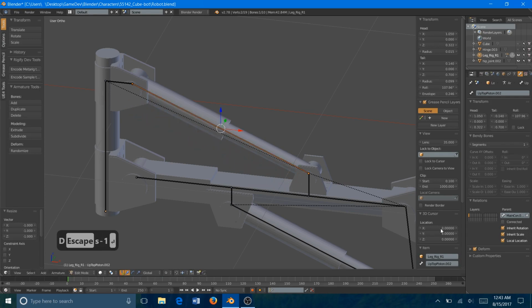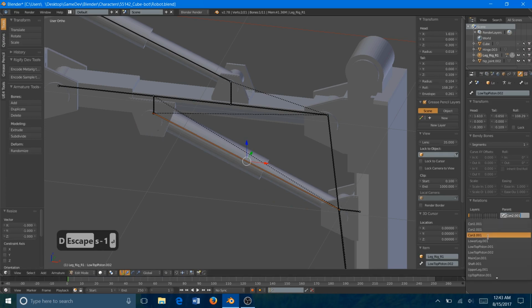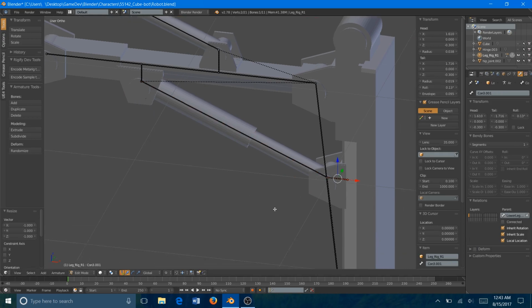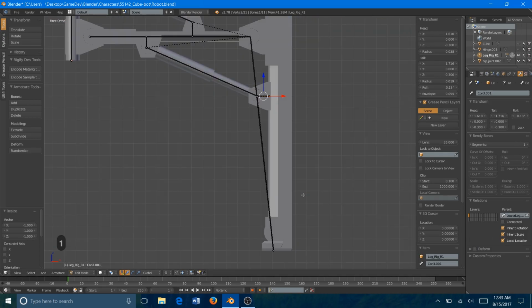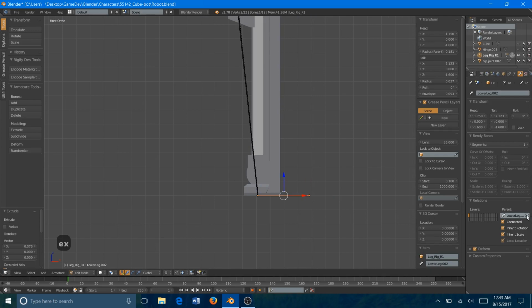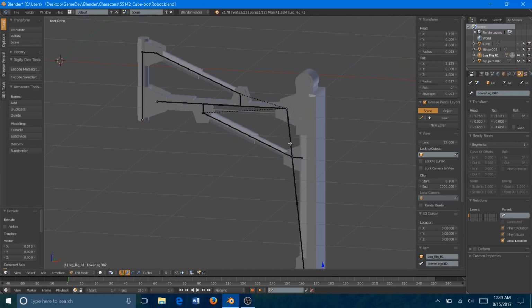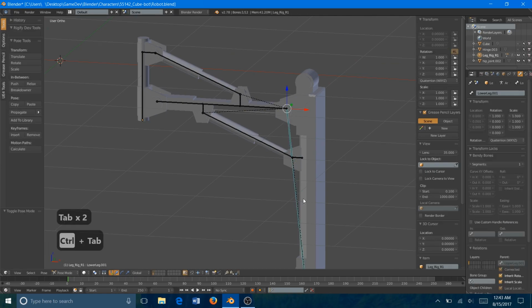Well, it makes sense. And here I'm duplicating the pistons and then connecting them to the opposite connector there. That's again just for the IK, so it works later. And then now I'm going to extend another bone here from the bottom of the leg, which is going to be my IK controller. So I'm just going to make sure it's not deformed, it's not connected to anything. And now I'm going to go and make the IK system.